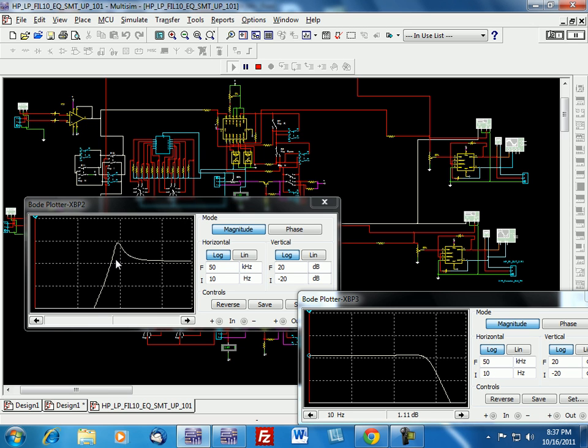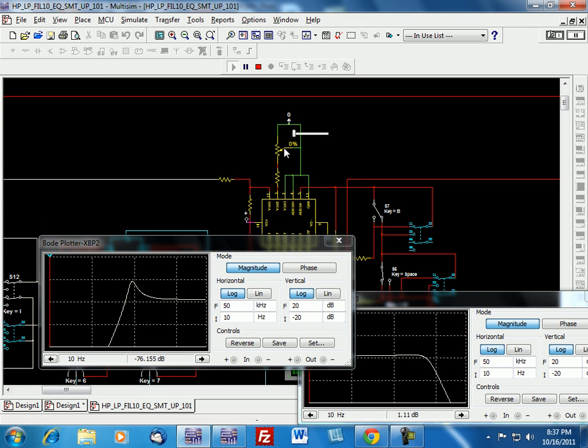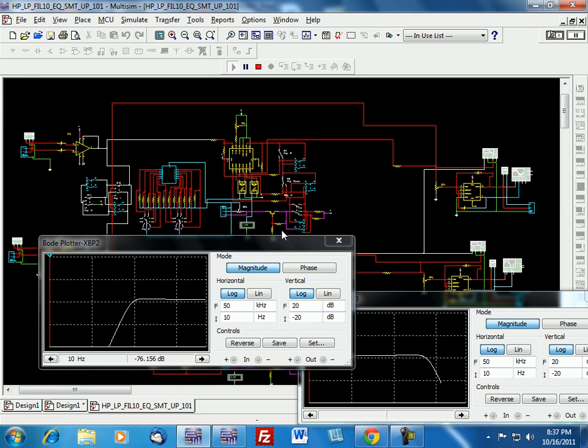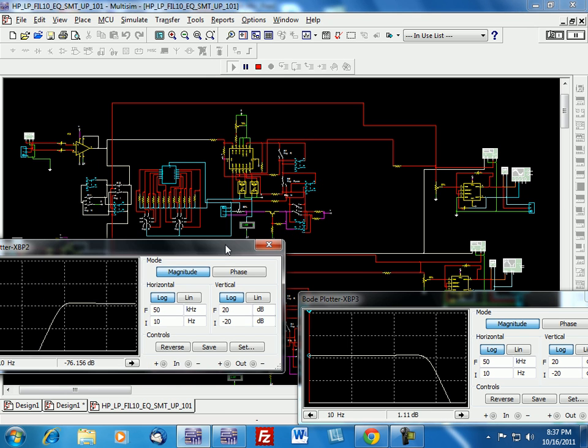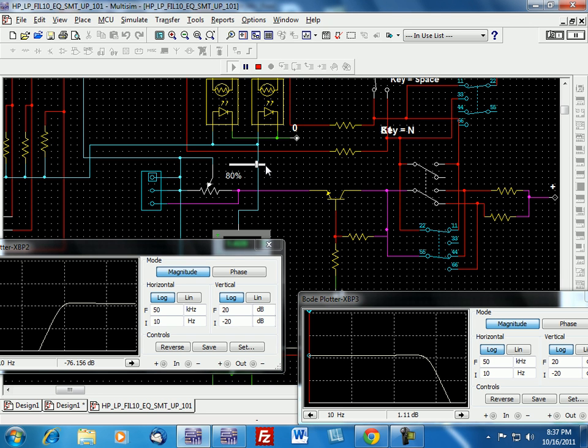Yeah, I purposely have this high pass here in this shape with the Q. It's adjustable Q. Let me go ahead and smoothen it out. Alright, and it can high pass or low pass. This is high pass, low pass mode, and I can adjust the frequency. It's voltage controlled high pass.